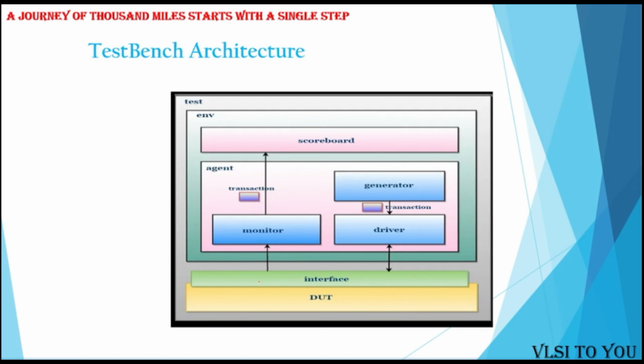Now, when we go back to Verilog, when you are writing code and a testbench to check that code, basically you will be writing the RTL design. For example, you are designing some 3-bit adder. For this 3-bit adder in Verilog, you will write the RTL code for the adder logic, and then you will be passing the values from the testbench.